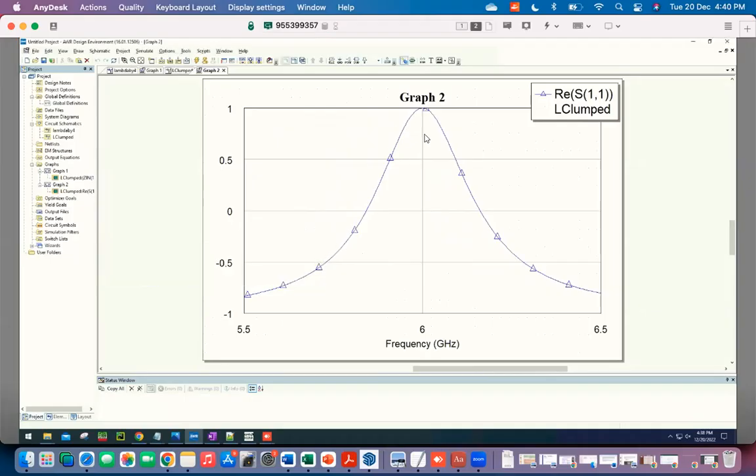Right. So remember the discussion from last time. I can look at the full width half max of this, and since this is a totally overcoupled resonator, there are no internal losses. I have not put any losses in the thing. Then those points are basically these two here. So this one is 5.844, and this one is 6.161. So it's about 160 plus 160, 320 megahertz, the line width of this resonator.